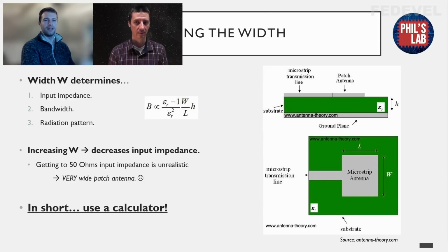Exactly. The problem is then you have to take into account not only the dielectric beneath, but also the core material and then the dielectric beneath. So calculating the permittivity is going to be quite a lot harder if you use a 4-layer board. Different materials mixed together. Exactly. So that's why usually for this, it's preferable to do it on a 2-layer PCB.